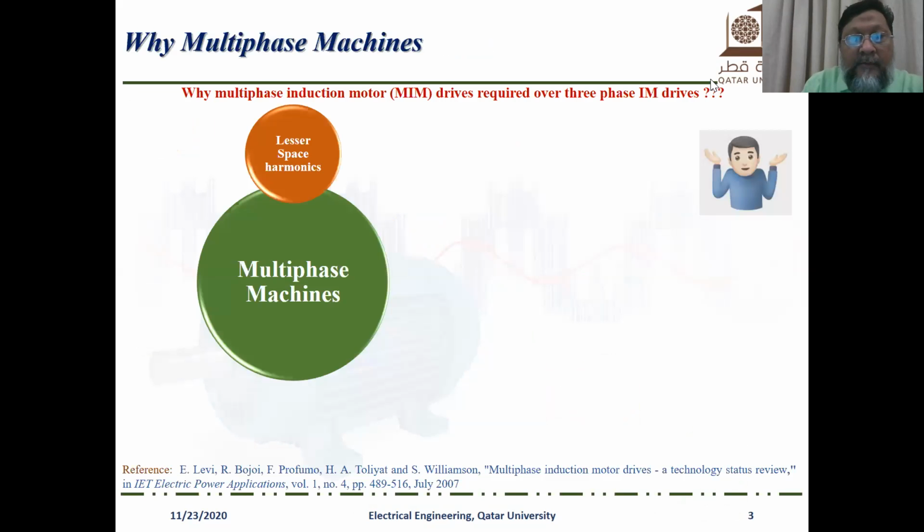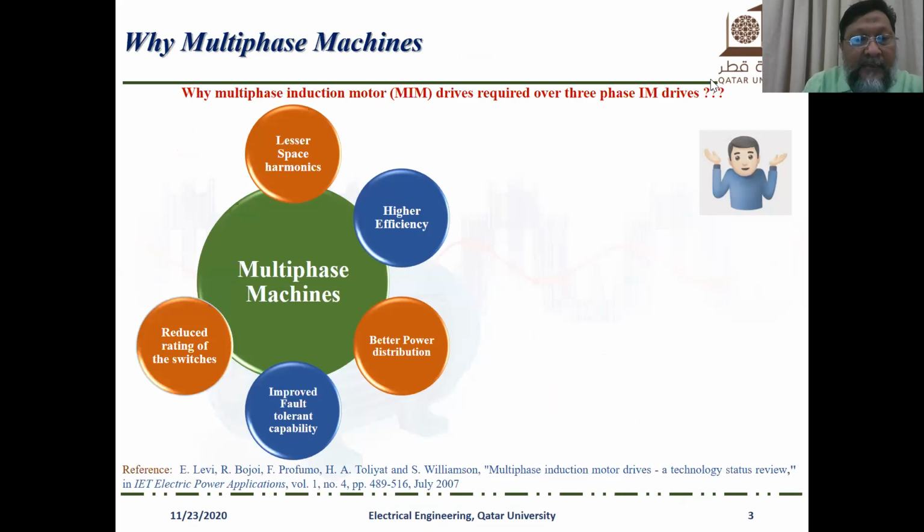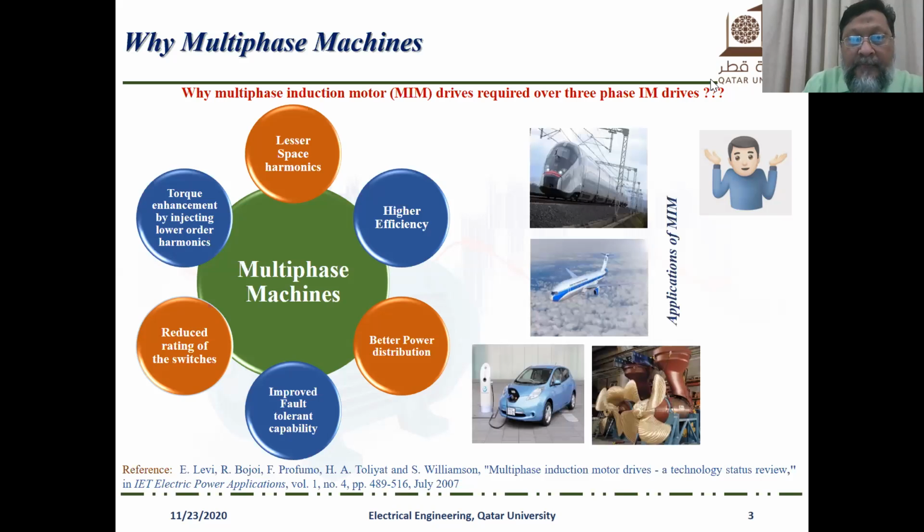Multi-phase machines have several advantages compared to three-phase machines, such as lesser space harmonics, higher efficiency, better power distribution, improved fault tolerant capability, reduced rating of the switches, and torque enhancement by injecting lower order harmonics. The application areas for multi-phase induction machines are more electric aircraft, electric vehicles, ship propulsion, traction applications, and